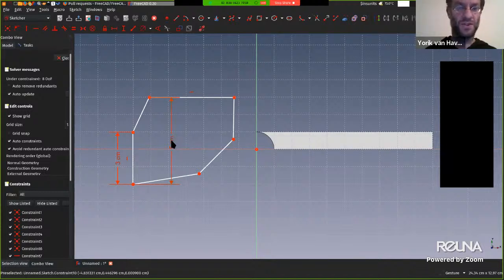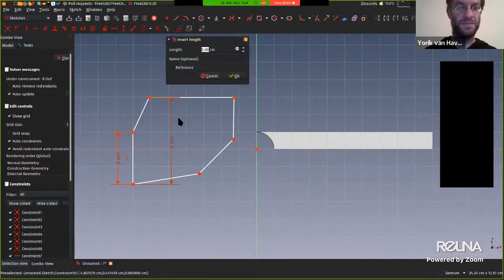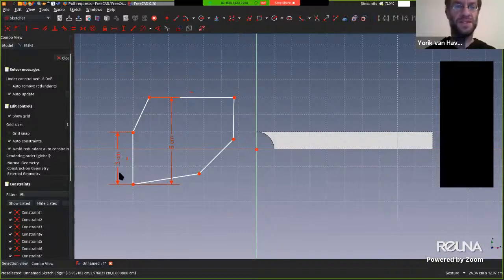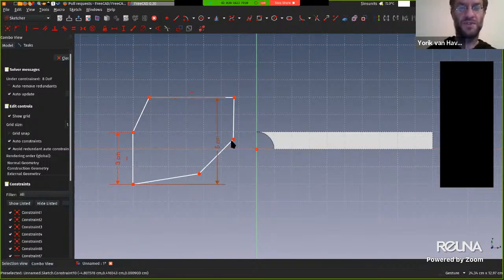You can also do things like, for example, this big dimension should always be 2 times the small dimension. And then if you change the small dimension, the big one will change its size automatically. So you can do really complex behaviors there, where one thing drives the other and the other and the other. And if you change one thing, all the other objects that depend on it will update.